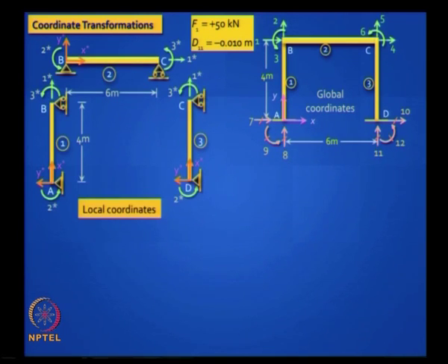Now you are dealing with 3 elements, and each of those elements has 3 degrees of freedom. 1 star corresponds to the axial degree, 2 star corresponds to rotation at the start node, 3 star rotation at the end node. Okay, and you can choose your start and end as you wish. In this case you can see that for elements 1 and 3 I have chosen the start node at the bottom. Okay, you have to generate this matrix, give it a shot.